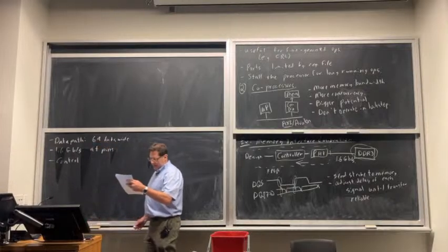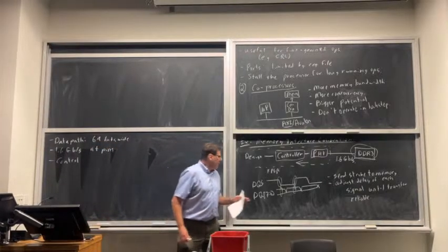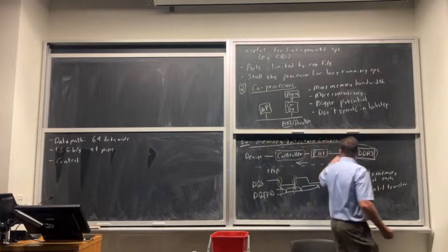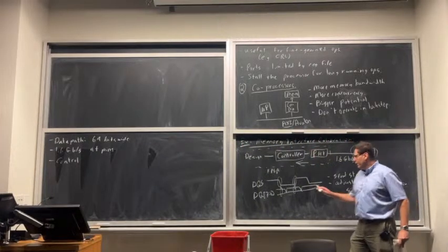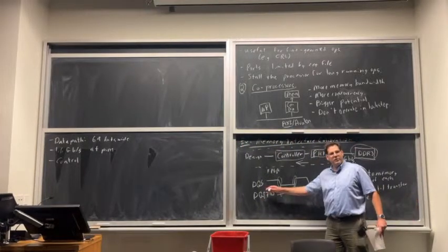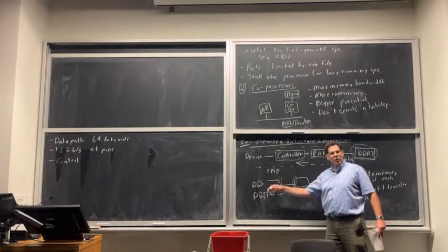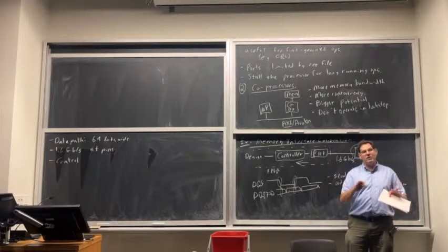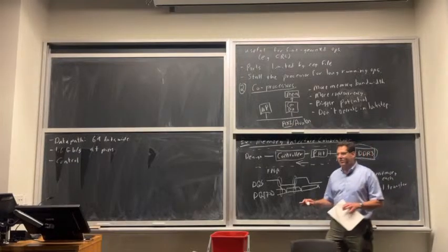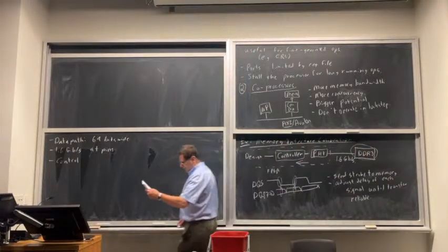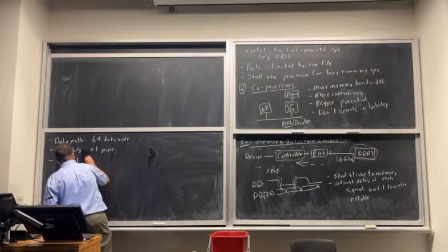And the control is complicated because, yeah, all of the complexity is on the FPGA to figure out how it shifts all of these DQ pins, how it shifts this strobe pin, how it should actually change that if it detects temperature is changing and so on. That's all on its problem. So control is this complex calibration algorithm.